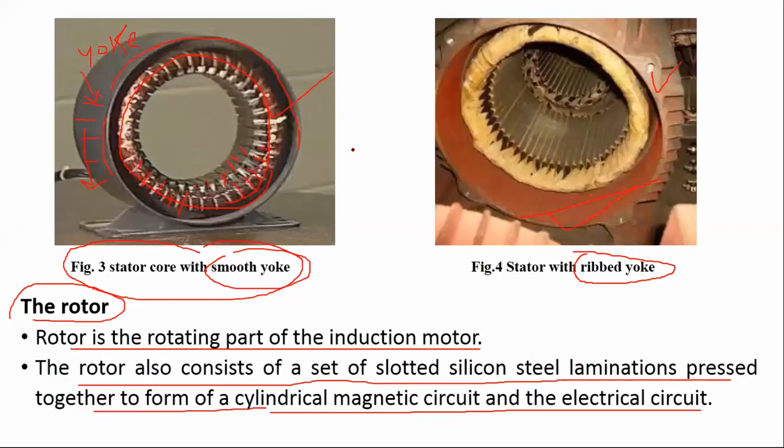thin laminated sheets are made in this way, and here this one which you see, these are the slots of rotor here. Okay, so thin sheets of this formation are made. This is for shaft. A number of thin sheets are made. They are laminated individually, and then they are pressed together. They are stacked together to form a block of rotor, right?